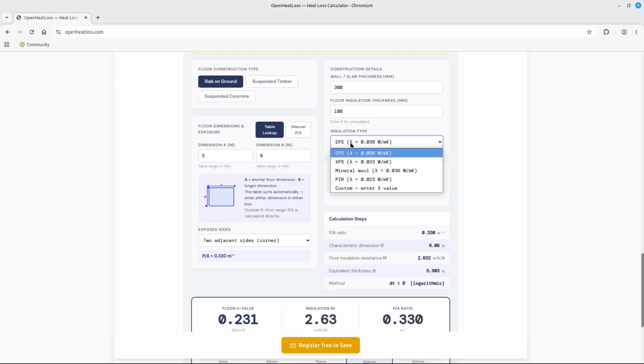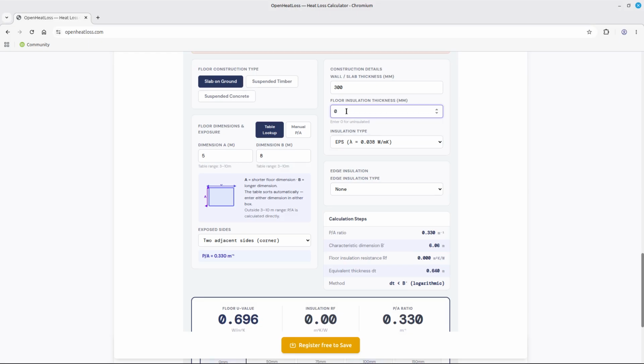Or, you know, this just calculates some standard rates, but you might have some different insulation. You might have had blown glass insulation because you're doing an upgrade to a cottage that was built in 1430, and they've dug out the whole of that floor and put in a load of blown glass insulation to allow the floor to continue breathing. So you might enter a different value, but don't worry too much about that for now, particularly if you don't have insulation. So we're going to put 0 on this one.